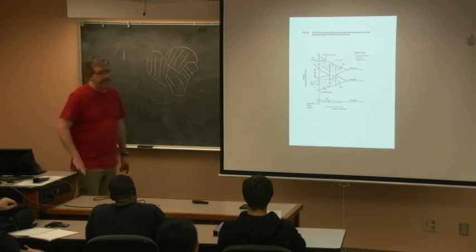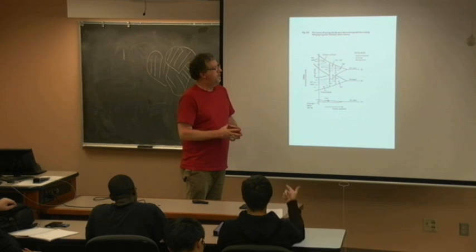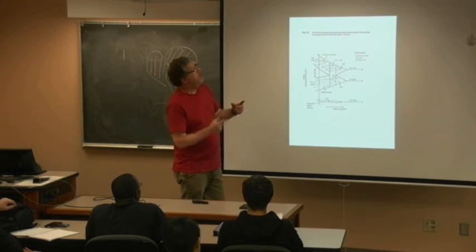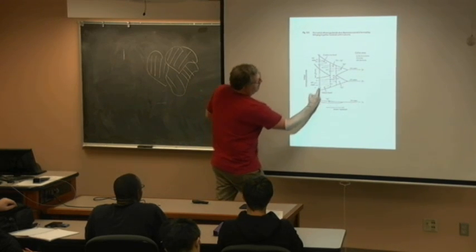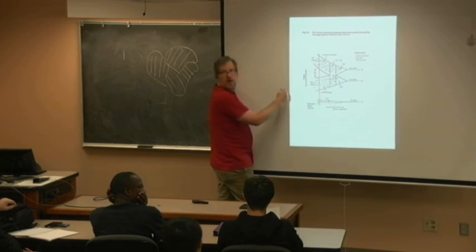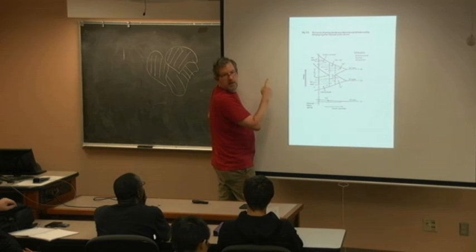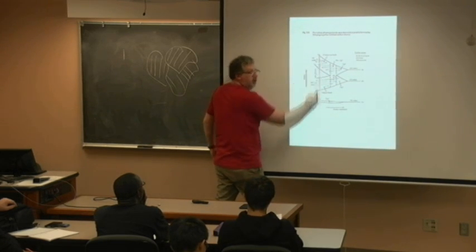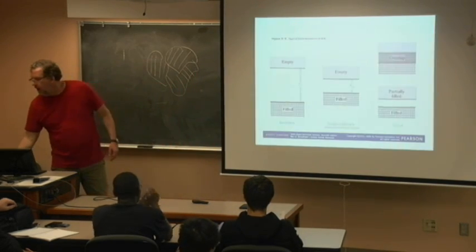Yes? So you said that for silicon, the sp3 hybridization happens. Is that this valence band? That determines the interatomic spacing. And so that's key. See, if this spacing was nudged a little bit here, a little bit there, see how my band gap shifts so dramatically? That's my key point. It's the lattice spacing, the crystallography, that's determining that band gap.